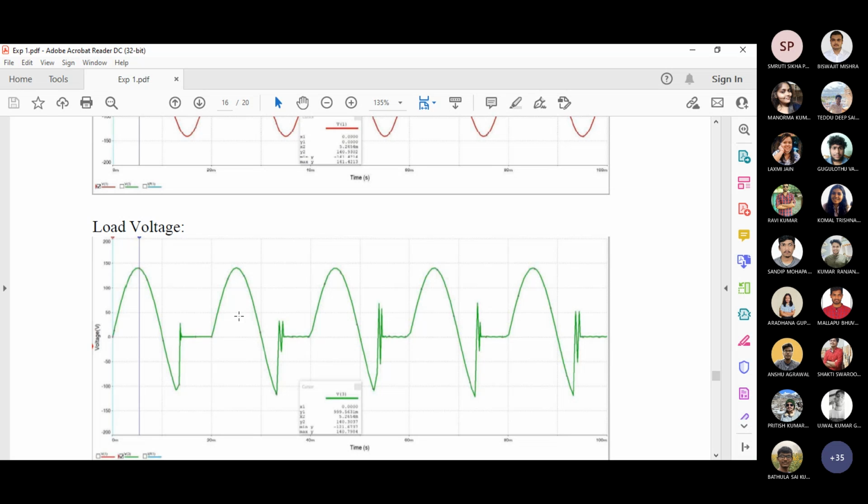So the specifications of the switch are also very important. It can run, but in that case you need to change the switch. Our agenda is not to change the switch, only to see the zone of operation, so fix the switch. Suppose 0.01 does not work; make the value somewhat larger and go up to 5. Take 10 samples: 5 just below 0.5, and another 5 just above 0.5 up to 5. That's the range you can see over your simulation, so 10 or 11 samples in total.